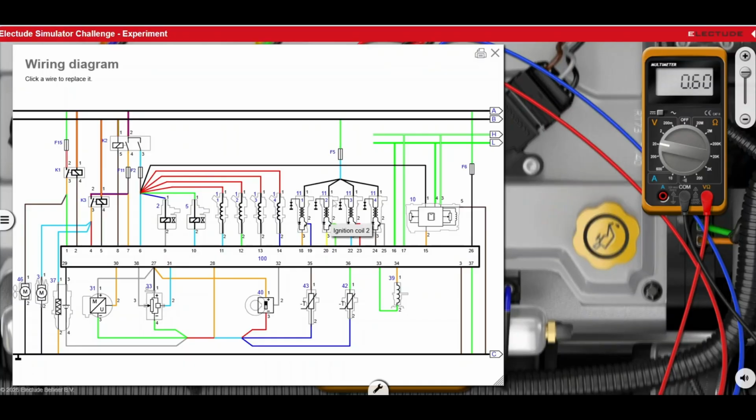These are the ignition coils. These are the injectors. All the red wires are supplying power to the injector. Then the computer will control the other wire on each of those injectors. It will control the other wire separately from the other injector, but they receive power from the same source. And then for the ignition coils, they receive power on the black wires. And then these are the spark plugs right here.